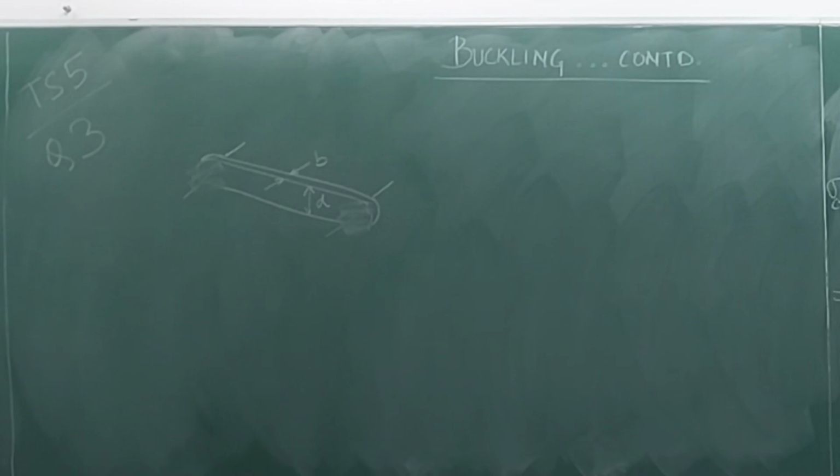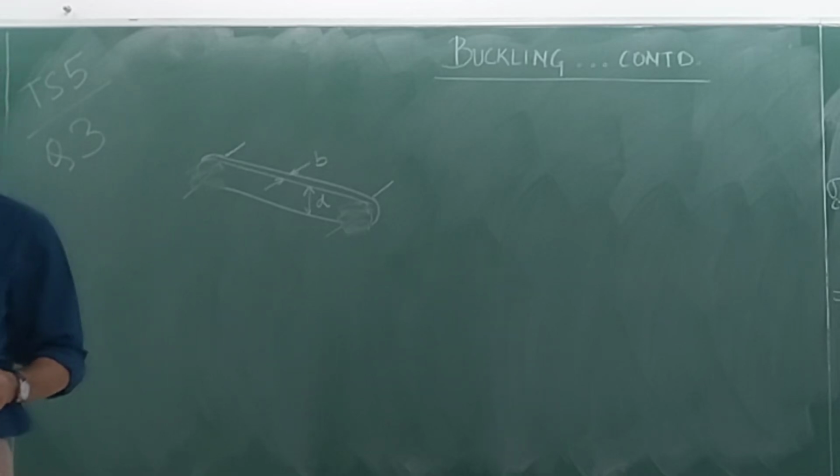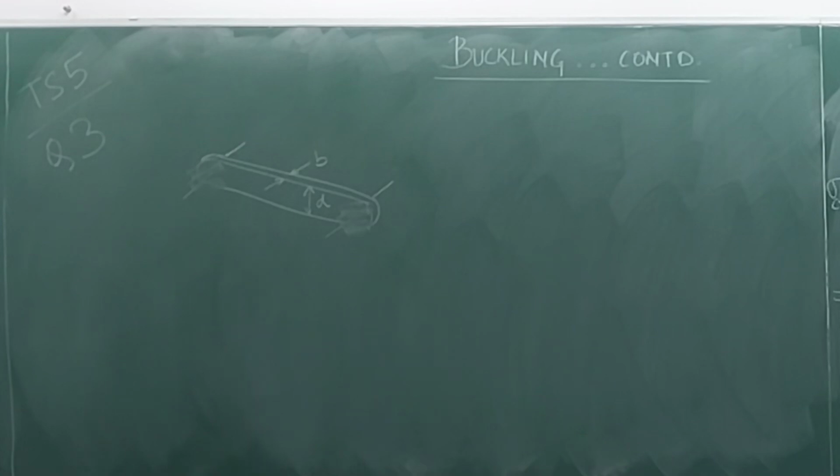And this is something which you will have to repeatedly do in many of the problems. This is a very, very standard problem scenario. You have two different planes in which buckling could possibly occur. You have to test it out and find some condition. So what do we do? First of all, we note that the two end conditions are different for the two cases of buckling. Okay, so case 1,